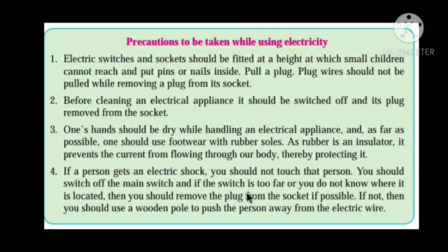And last, if a person gets an electric shock, you should not touch that person. You should switch off the main switch, and if the switch is too far or you do not know where it is located, then you should remove the plug from the socket if possible. If not, then you should use a wooden pole to push the person away from the electric wire.